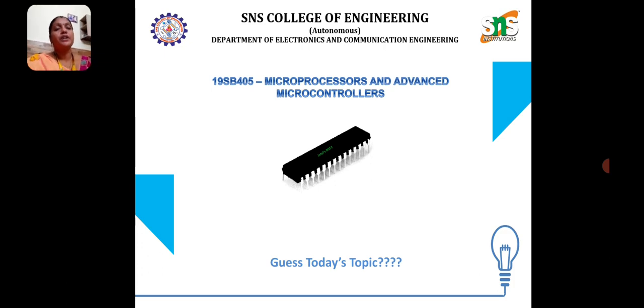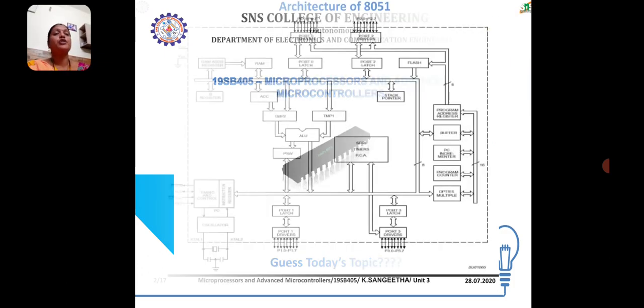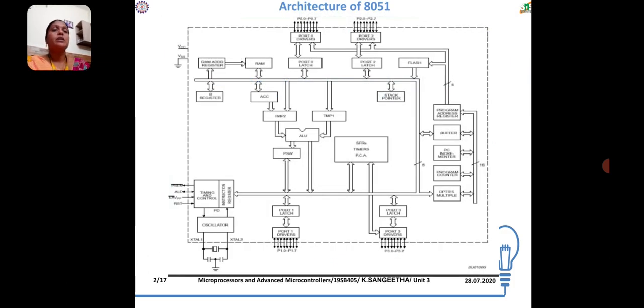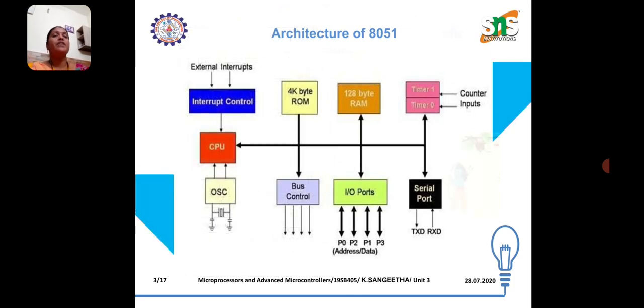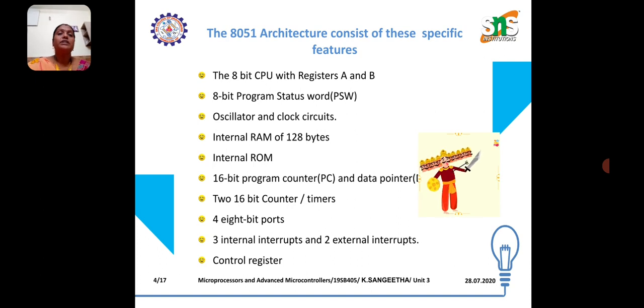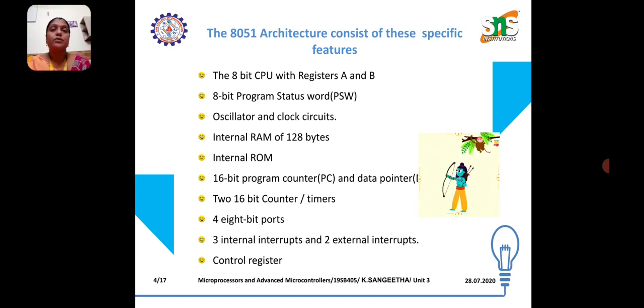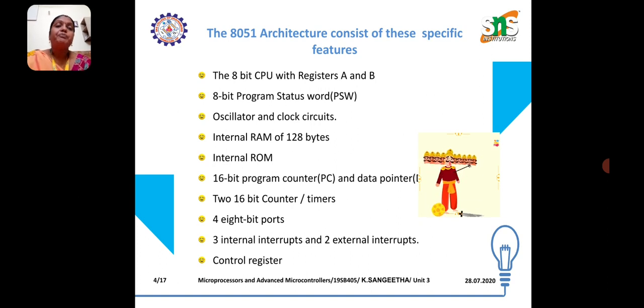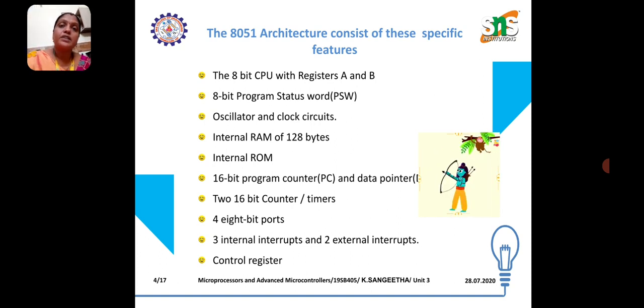So today we are going to discuss the 8051 microcontroller. First we will see the main features of 8051. It is an 8-bit CPU with registers A and B. 8-bit CPU means the data bus width is 8-bit, and the next one is the address bus, which is